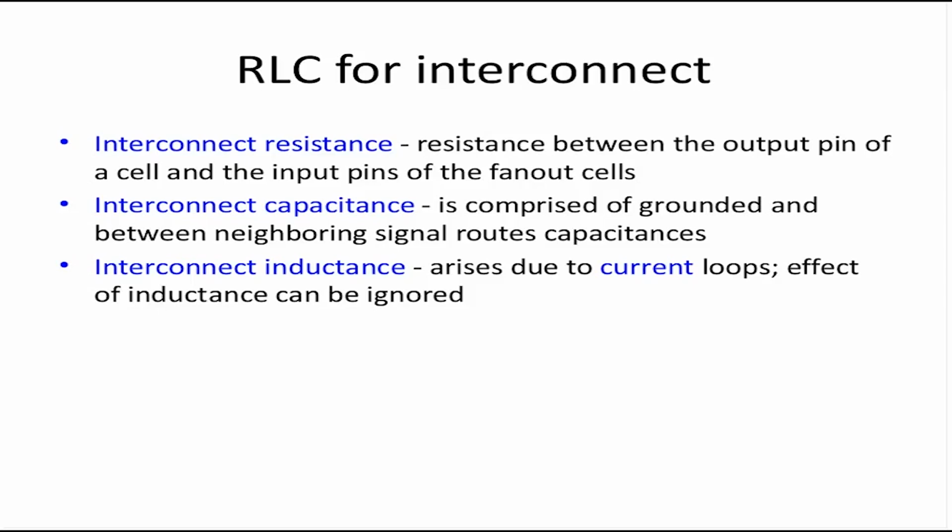And why are they undesirable? Any resistance will consume power, will make the chip heat up. So obviously our target is to reduce the resistance as low as possible. This is why copper interconnect is very popular. Again, capacitance: the higher the capacitance, the more time, the more current needed to charge it up to VDD and then to discharge it to ground. So the more net delay. That's why again there are techniques to reduce capacitance. You would probably study in one of the fabrication courses.